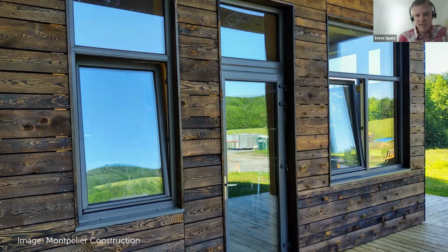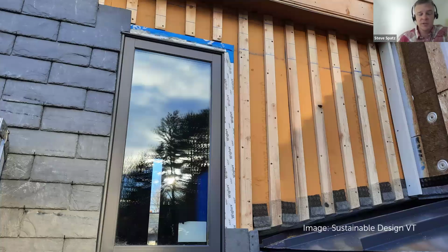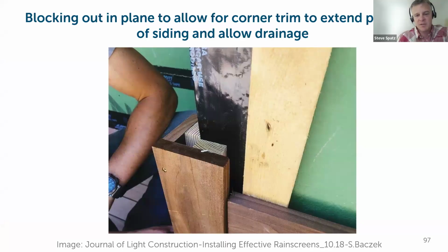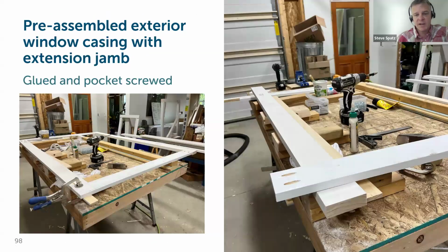So there's different aesthetics that can come into play when doing open rain screen sort of exterior finishes, and that aesthetic can build to what the look of the building will be, but also it doesn't have to be some modern aesthetic or use some specific material choice. You can also do more traditional quote unquote exterior finishes as well. But just creating, again, this pathway for water to not collect and be trapped in any specific area, but simply to be able to dry out.